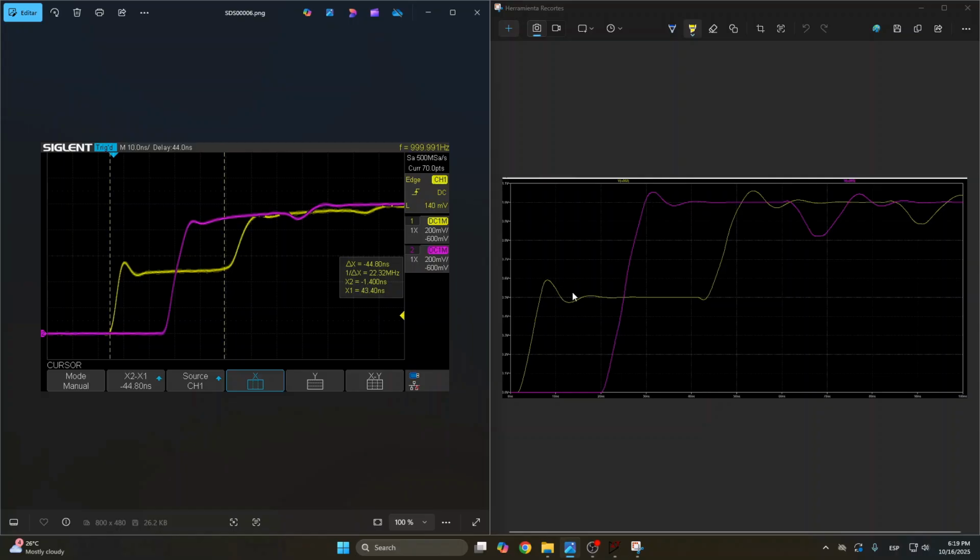These additional pulses, we can call it noise or ringing, are caused because those additional components that were not in our initial simple simulation produce additional reflections. So these are tiny reflections that settle down very quickly, but you can still observe them.